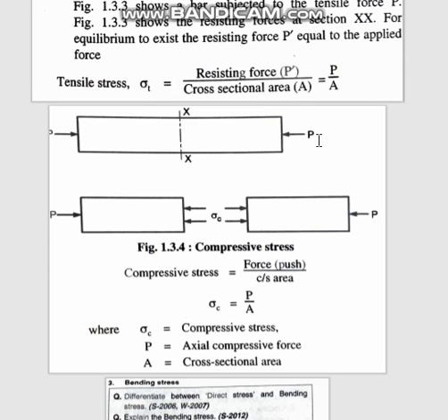You should observe things properly. You see, observation is one essential requirement for a good student. Whether this P arrow is going outside or inside. You see, if it is pressing the component, that means it is under compression. So again at the cross section, you see now the arrows here are in the opposite direction.